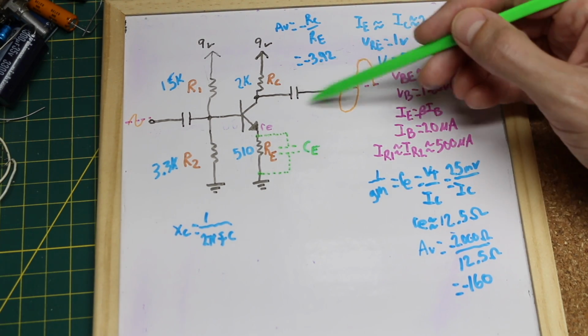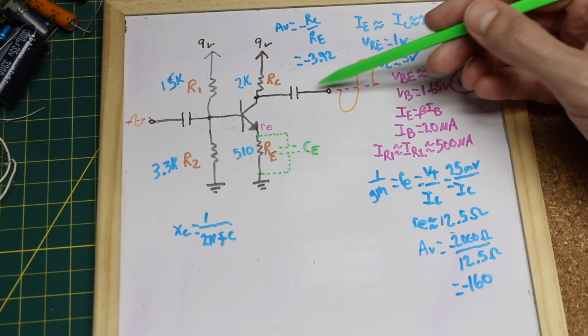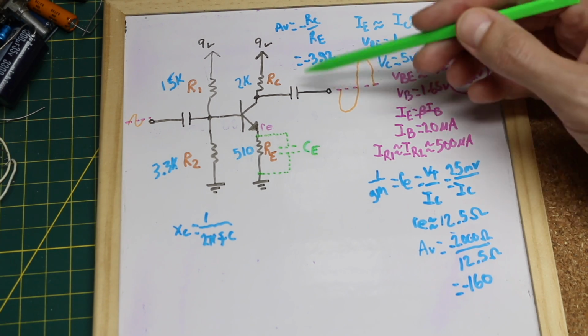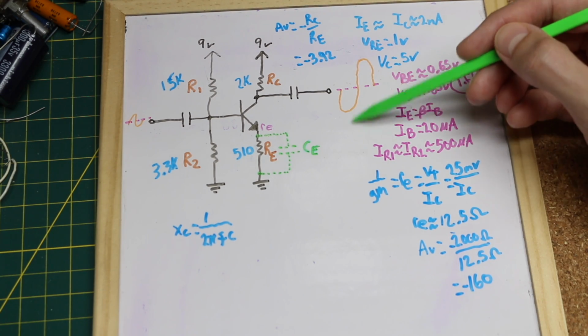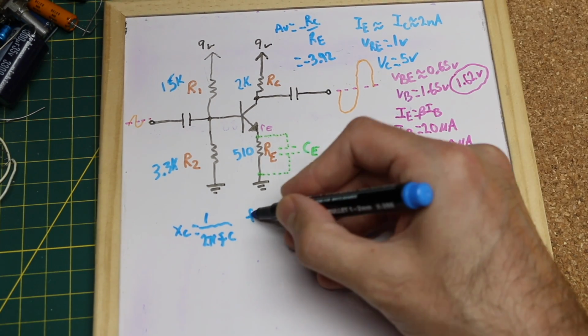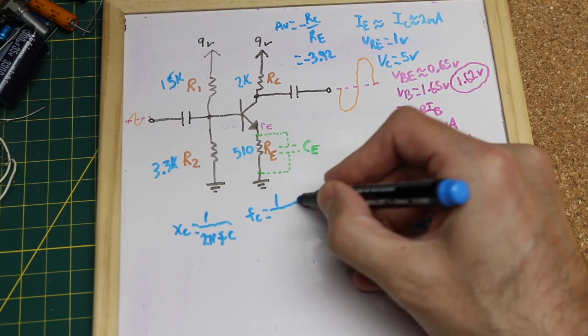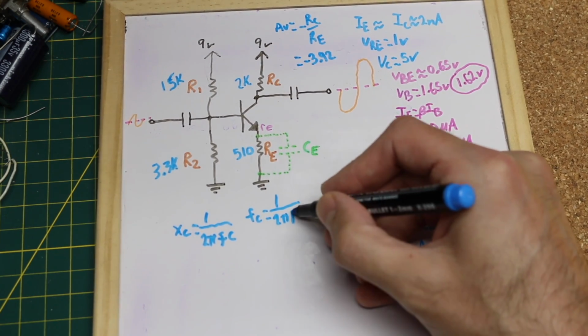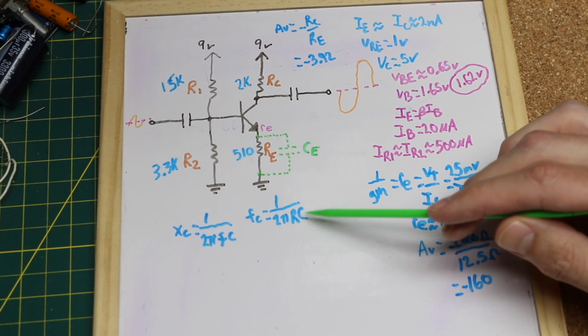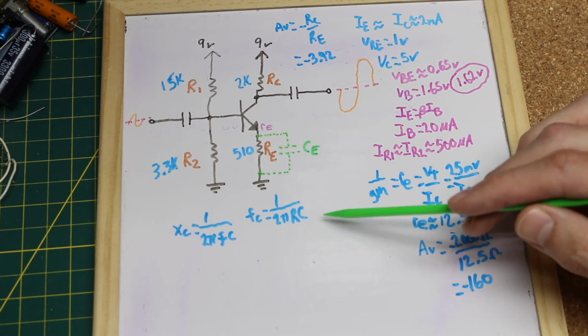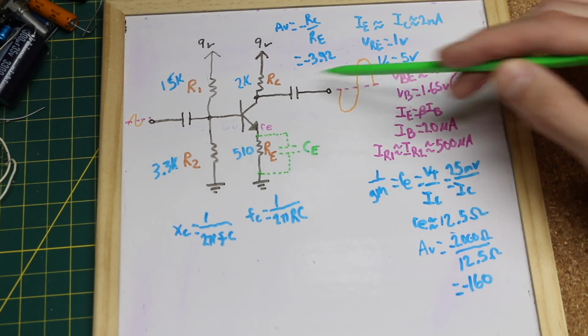So if my lowest frequency of interest will be 20 Hertz, where I want to calculate a minus 3 dB filter cutoff, I can just substitute in 1 meg arbitrarily. So then filter cutoff 20 Hertz equals 1 over 2 pi resistor, large 1 meg, times capacitor. So I can solve for capacitance to give me that sort of frequency response.